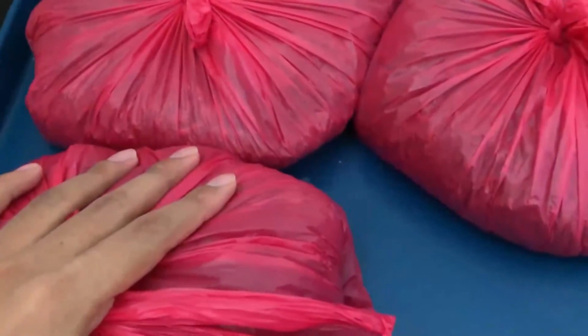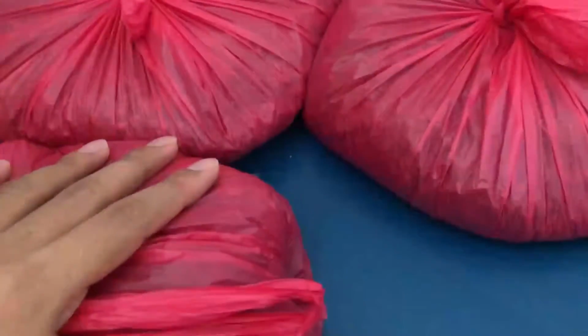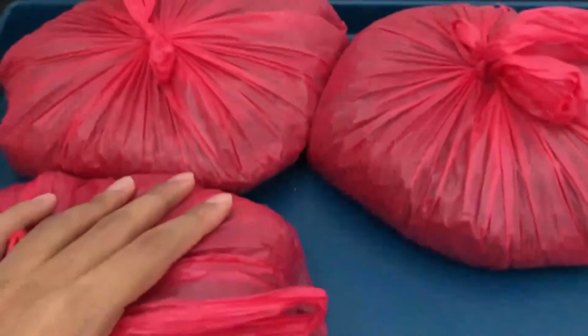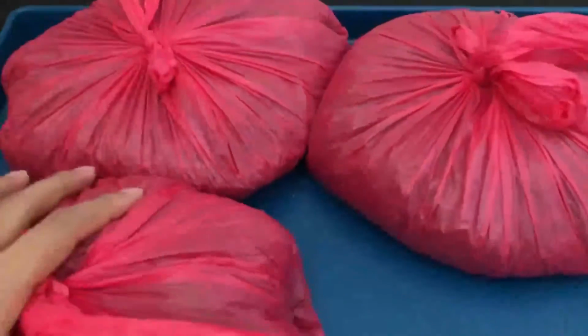The water content is also used in expressing the phase relationship of air, water, and solid in a given volume of soil. So the material and apparatus that I use in this experiment is soil, tray, and digital scales. The first step is to split the soil into 3 parts. So I've split it into 3 parts.